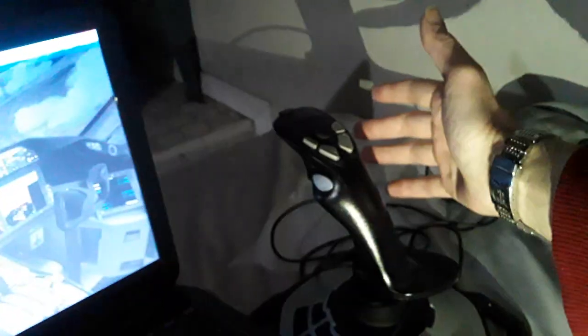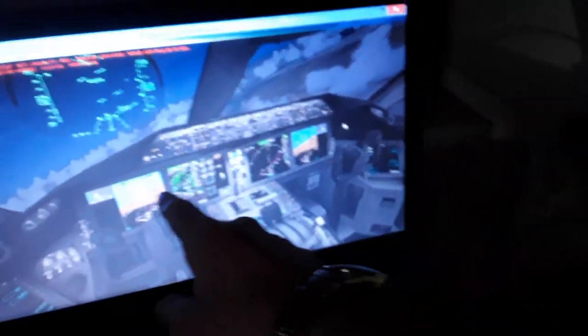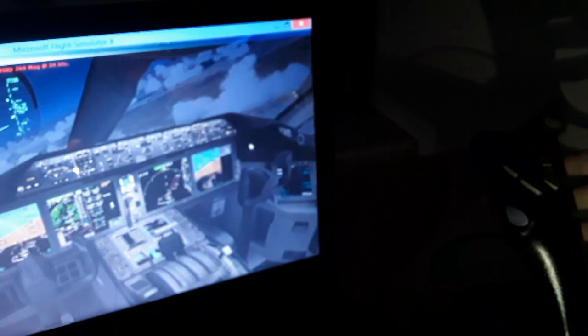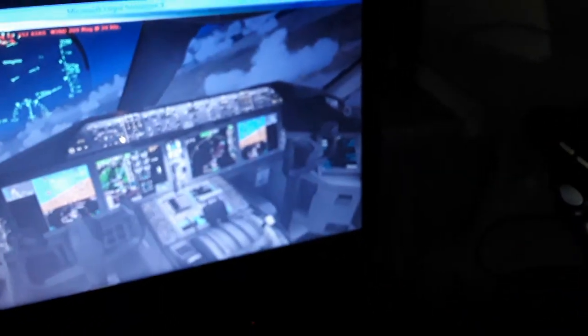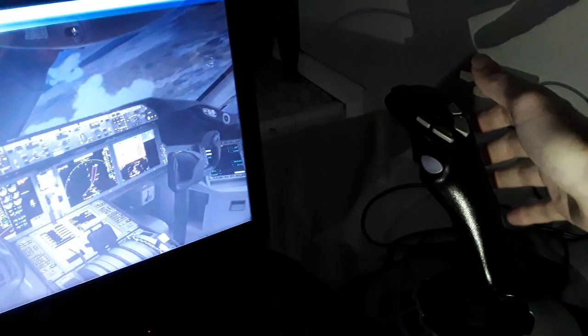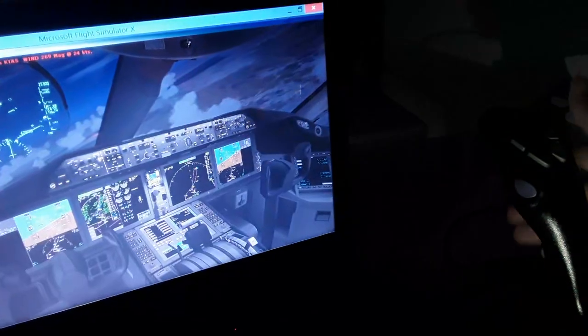So you can see we can leave the hands off from the side stick, no problem. The aircraft keeps its attitude, its airspeed, heading, everything, even though we have no flight controls or autopilot connected. Only an airplane can do that. In the air, you can fly with the hands off when you trim as much as you should, and you use the